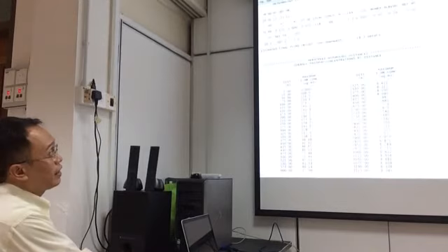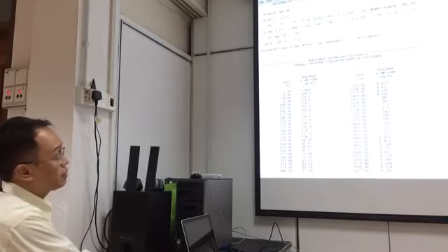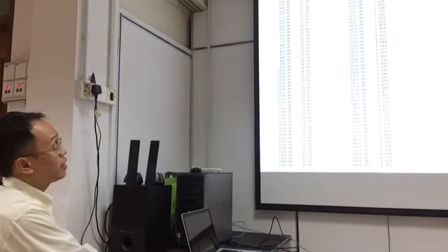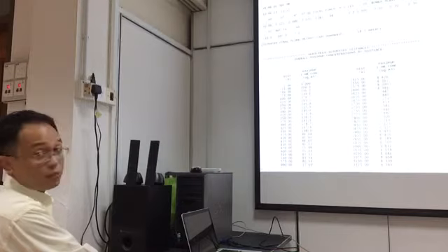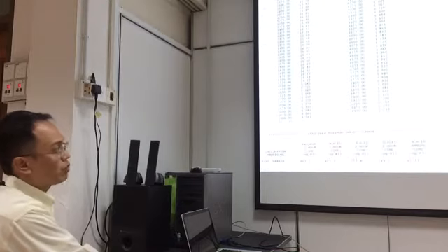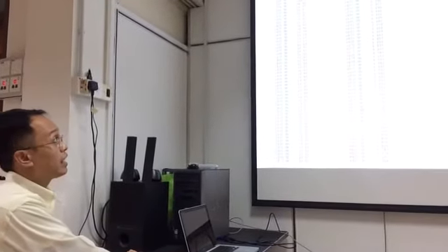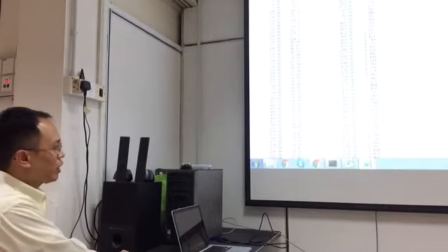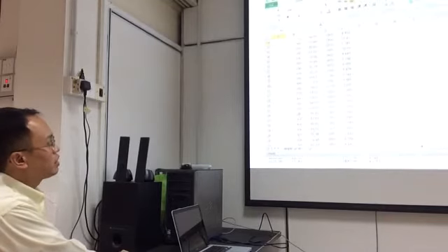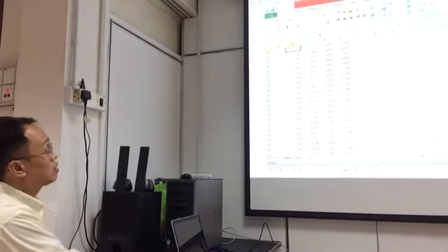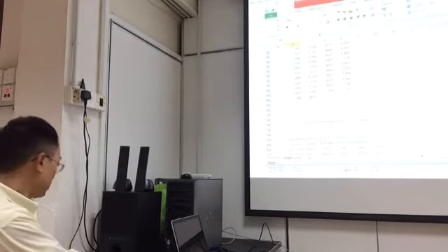So notice this line here. This is the result, AERSCREEN automated distance. Okay, distance, maximum 1 hour concentration. And then this is the second, it's still distance. That means 1 until 2,500. And then it continues up here until 5,000. Remember the distance to probe, the maximum distance up to 5,000. And then the concentration is this. So if you go back to Excel, see this is 1 until 2,500. So if you want to plot this, you just choose these two columns.